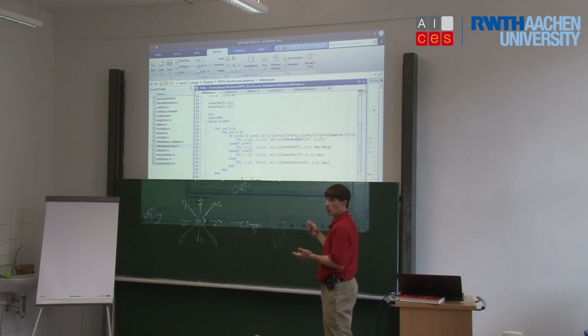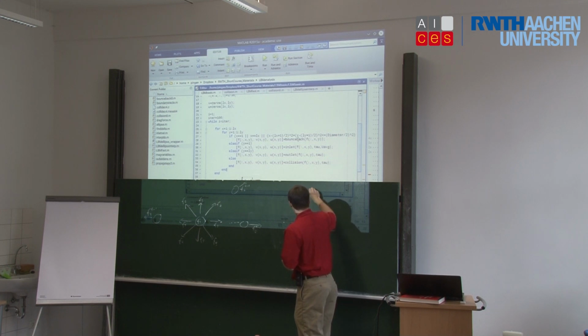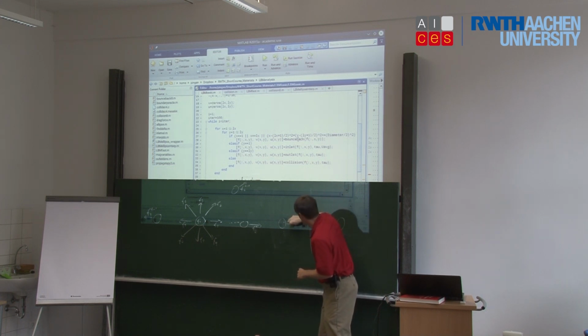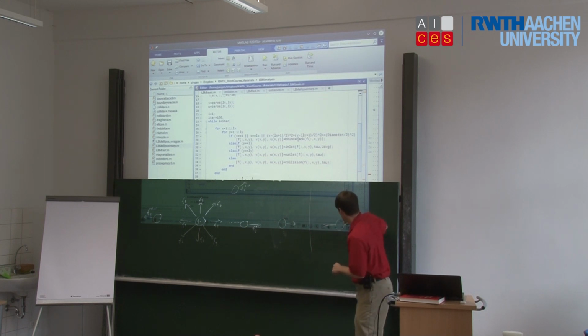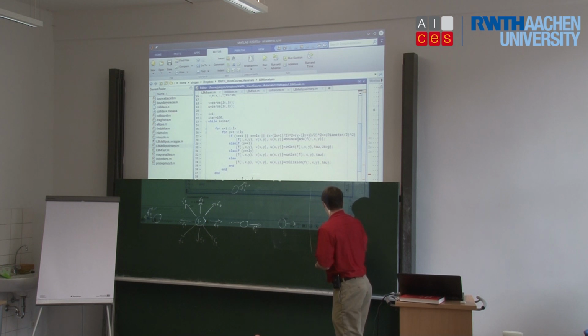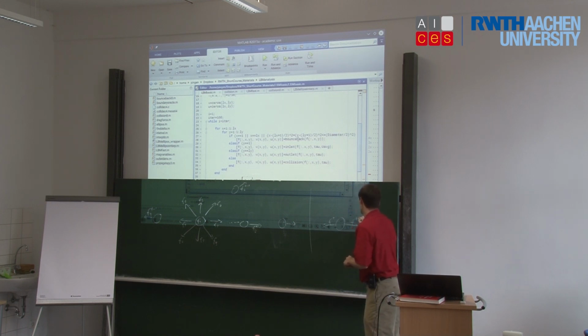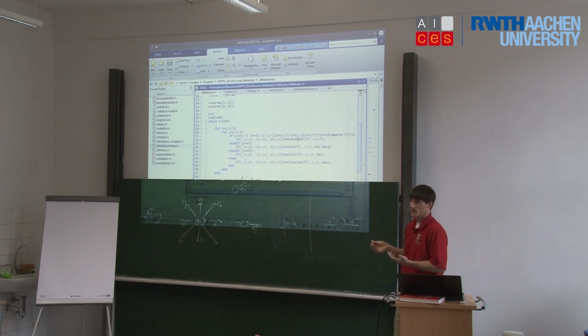What we've looked at is we've only looked at the basic bounce back boundary condition. Basic bounce back says that the wall is halfway between this, and whatever travels in this direction will go here, it will be reflected, and in the next time step, it will move back to right there. So whatever starts here at f t will end up right here at f t plus 1, basically. Okay. So that's the basic bounce back condition.